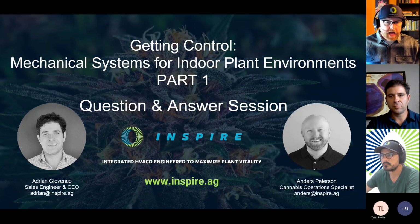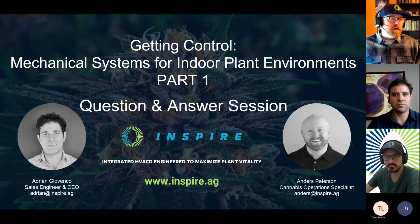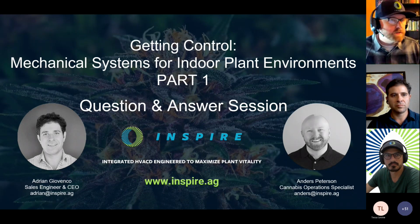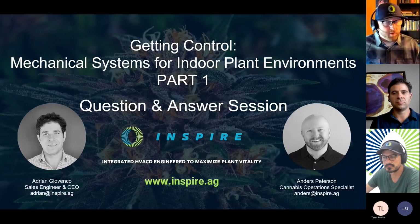It's especially true today as these sensors and IoT devices have gotten so much cheaper. There are a couple of different approaches. There are cameras that try to ignore the ground and the benches and hit only the canopy to get a good measurement at the right angle. And then there are leaf calipers that have a little thermistor underneath the leaf to measure the temperature. You can plug a bunch of them in around the room. Those are both ways in which you can automatically monitor and data log in a space.